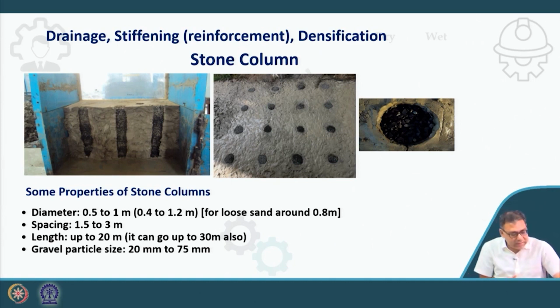Now, there are different installation techniques available, such as the dry method and the wet method. Depending upon the soil type, because remember that ours is loose soil, and the site condition, we will decide which technique to use to install this stone column. Clear? So right now I will mainly concentrate on the design part.